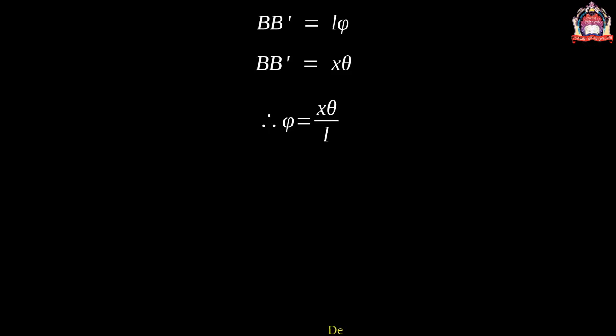Your hand is fixed at the shoulder side, so their minimum displacement takes place at the shoulder. So shearing stress is not uniform all through this. In a similar way, here, although the angle of shear is the same for any one hollow cylinder, it is different for different cylinders, being the greatest for the outermost and the least for the innermost one.